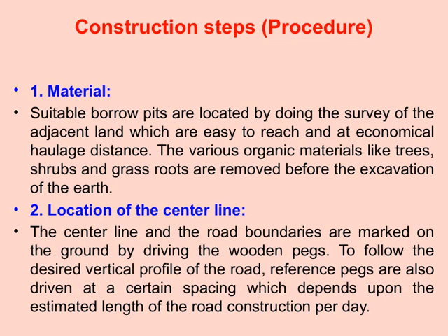Let's talk about the construction steps involved in the procedure. First, when it comes to the material, it's important to identify suitable borrow pits. These are typically located by surveying the land adjacent to the construction site. We look for areas that are easy to access and at a reasonable haulage distance to keep costs down. Before we begin excavation, we also need to remove any organic materials like trees, shrubs, and grass roots, as these can affect the stability and quality of the earth we're working with.